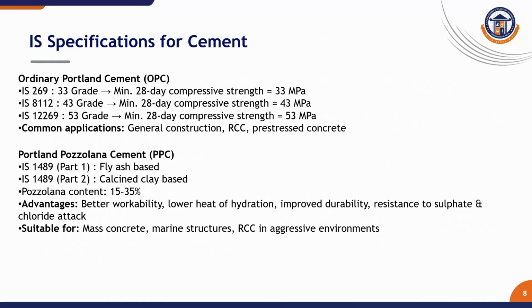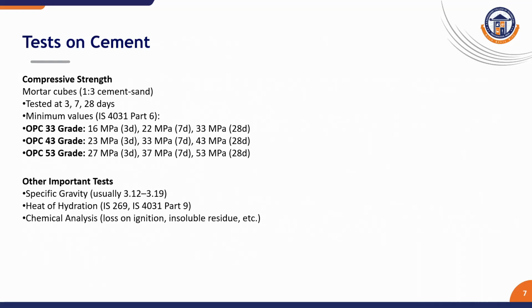The magic of concrete hardening happens through hydration. It is a chemical reaction between cement compounds and water forming hydration products that bind the mix and develop strength. This reaction is exothermic, meaning it releases heat, especially in the first 24 to 72 hours.